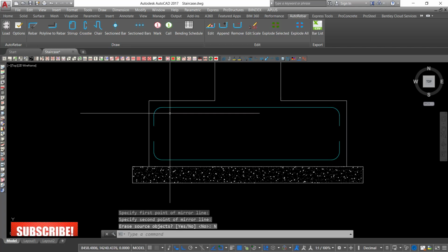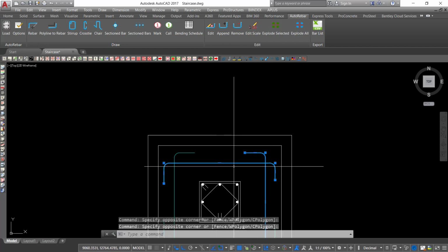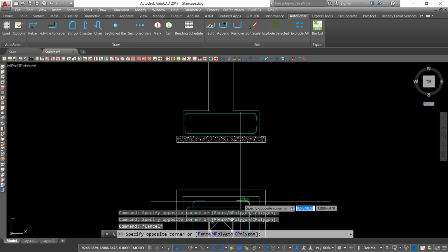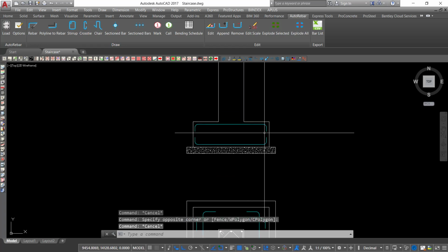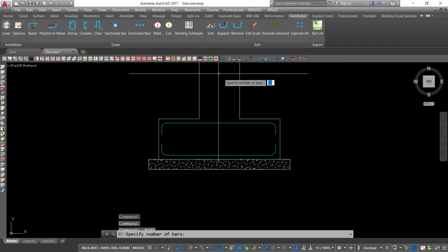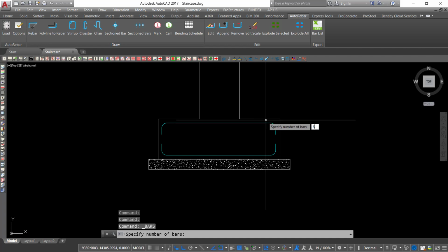So I need the vertical, I mean, I now need these bars. I want to highlight these bars. I've already highlighted this, so I want to bring the elevations for these bars here, the ones I've selected. I'll only be able to see the section of it when they are cut across. So I'll come to bars section here, and once I click on the bars section, I'll need approximately 6 bars distributed at 200 center to center.